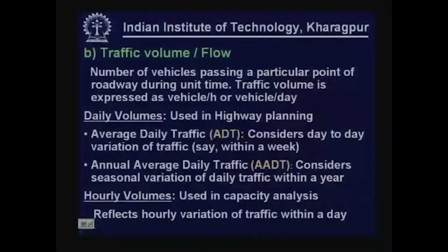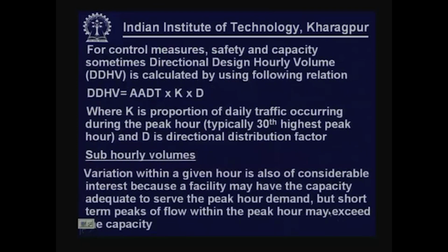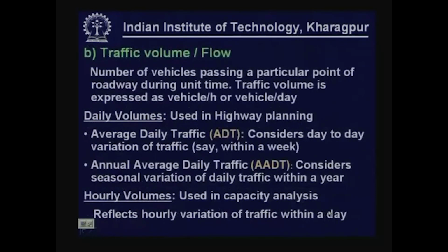We also express traffic volume in terms of hourly volume, and this is normally used for capacity analysis. This normally reflects hourly traffic variation within a day. So, you may find that maybe during the peak hours from 9 to 10 in the morning and maybe again 5 to 6 o'clock in the evening, you have heavy traffic. So, we can use that type of measurement for capacity analysis.